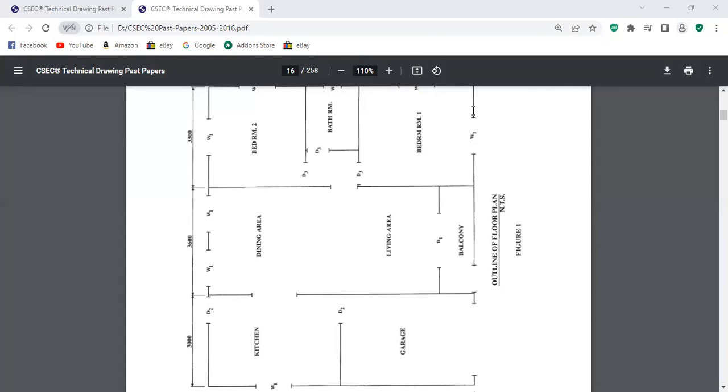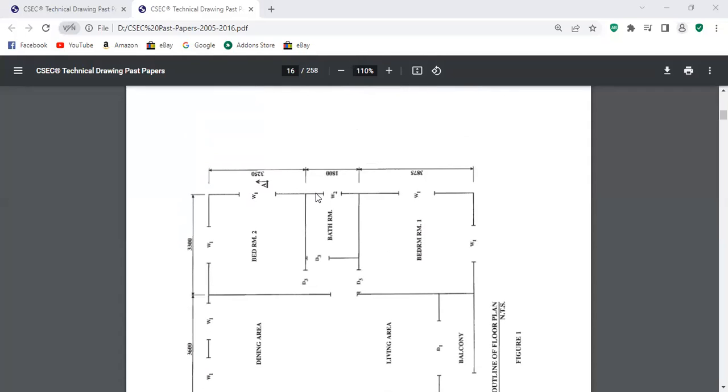By the end of this video, you should know how to draw the sectional elevation for a floor plan using AutoCAD Architecture. In my previous video, I explained how to generate the sectional elevation using standard AutoCAD. But in this case, I'll be using AutoCAD Architecture. This version is way easier than the novel AutoCAD.